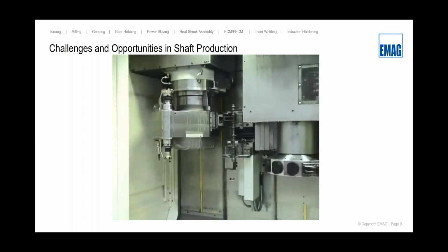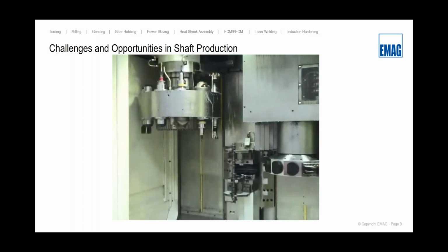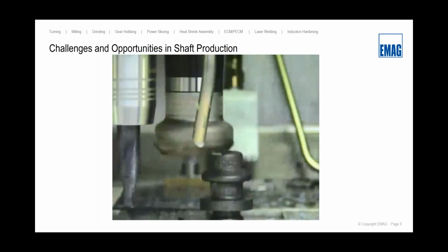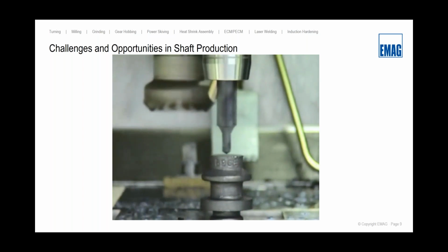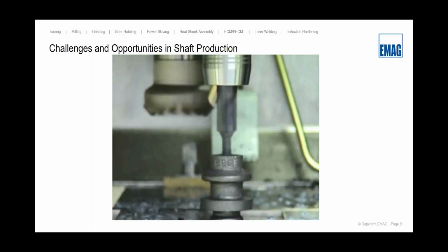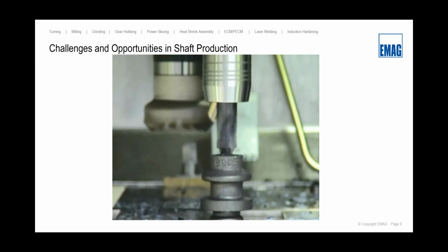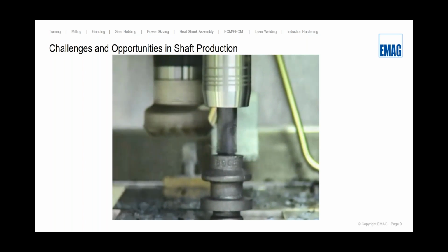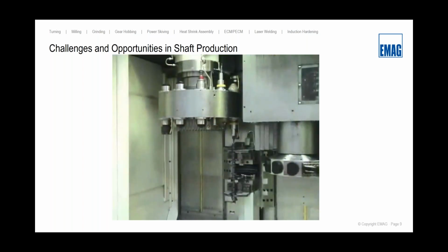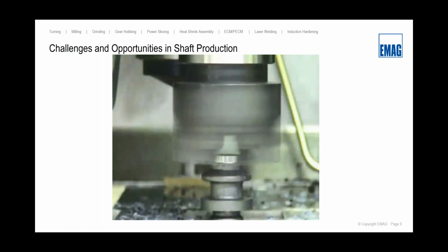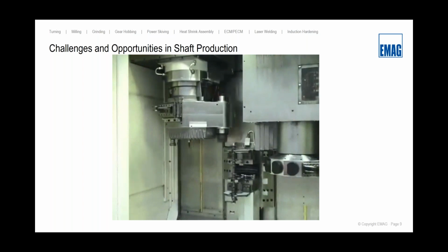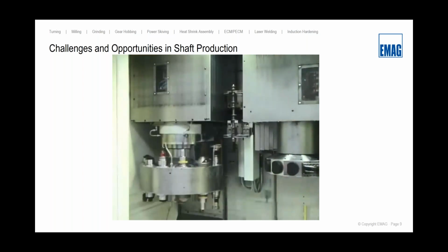So you see that my turret here, we call this one on the left our big elephant's foot, had a gripper on the back side of this turret. The front side has all the milling tools, the back side has that gripper. And this also fits into Emag's principle of machine design. We always want to be self-loading, use the machine to load itself.